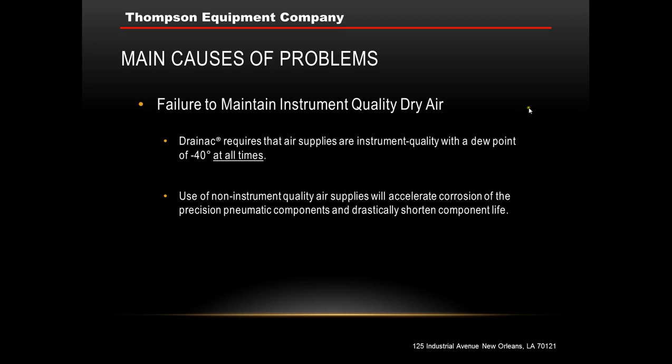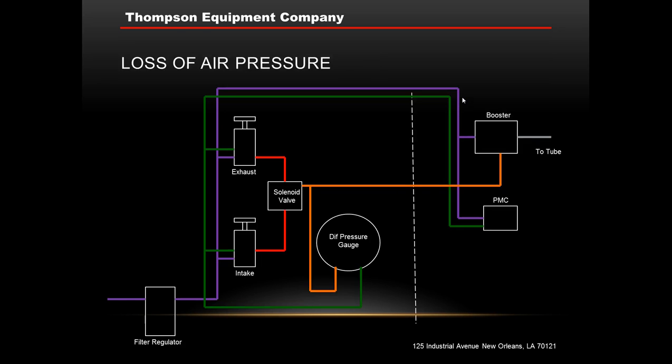If you don't maintain the quality of the dry air, the air supplies need to be instrument quality with a dew point of -40 degrees at all times. If you use moist air, that will accelerate corrosion of those precision pneumatics as well. And again, shorten component life.